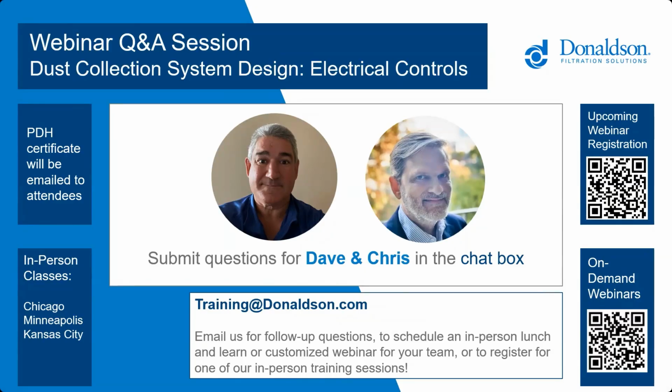In a very big weld school, let's say you've got 40 different student weld booths and you only have 20 students, systems can be designed in zones. It's probably not practical, and I defer to your experience, Dave, to cut off each and every little weld cell where somebody's not at, but you do it in zones. So if you don't have a full class or a full room, you can cut it in 4 different zones and 10 people can weld, or turn it all on for 40 people to weld. I've seen that in weld school design.